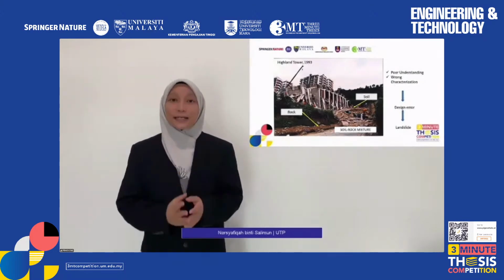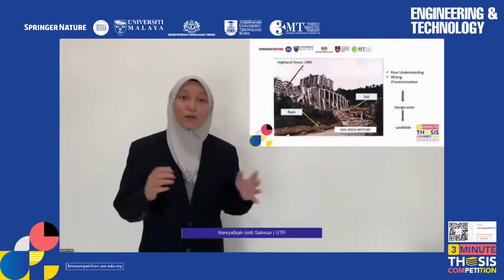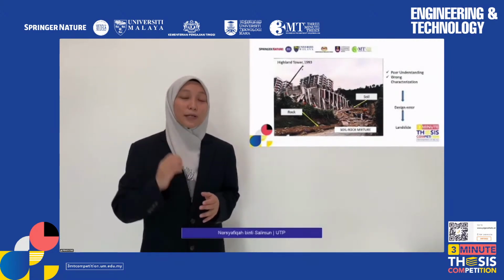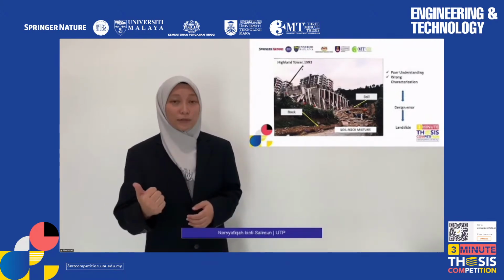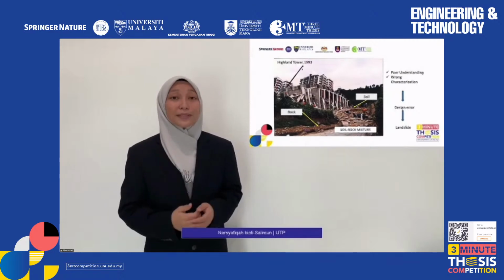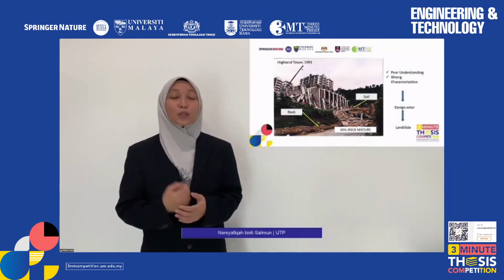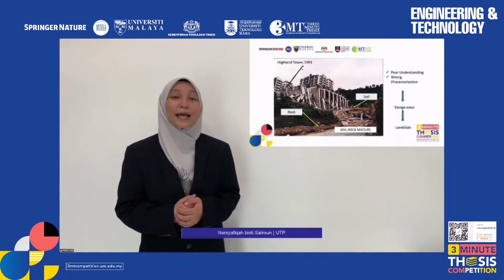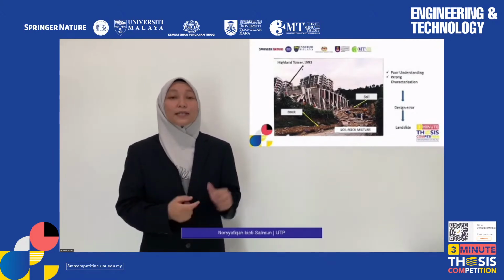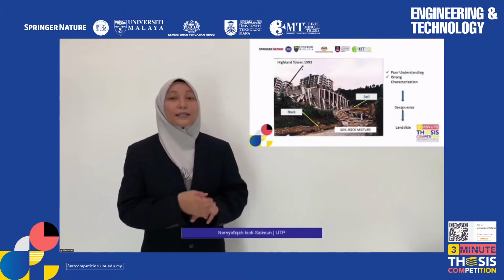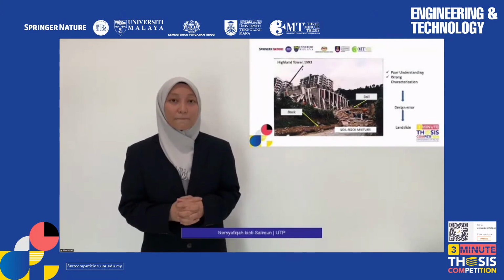Previous study had shown that the shear strength of SRM is largely controlled by the rock block proportions and the granular distribution. However, there are significant factors such as moisture content, soil type, and rock block shape that are limitedly studied. My work is to determine the influence of these factors towards the SRM mechanical properties, and we came up with two significant conclusions. The first one, we determined that the moisture content, the soil type, and the rock block shape actually influence the interlocking force between the composed material in SRM.